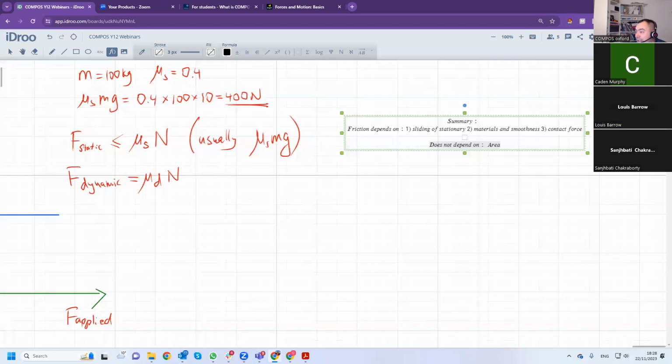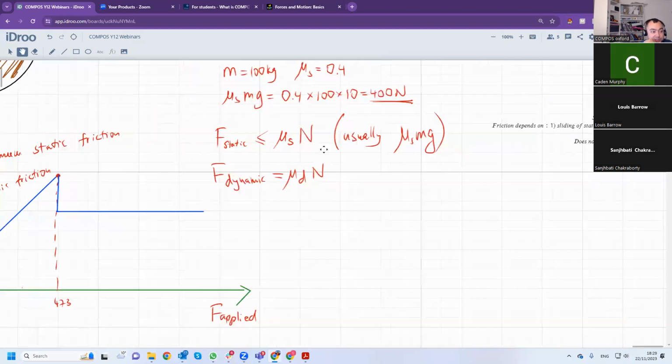Yes, the coefficient of friction is usually given to you, or they ask you to find the coefficient of friction. I was thinking along the lines of the boundary between static and dynamic friction. You can think of static friction as being set into the gaps, and when you push, it jumps out of the gaps, so the friction is smaller. If you try to move a heavy fridge or anything heavy, you will notice that it is harder to get it moving rather than to keep it moving. So dynamic friction tends to be smaller than static friction.